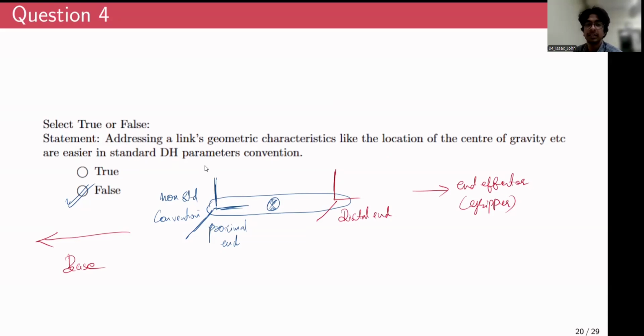So the major thing some people are still going for standard representation is that in that general transformation matrix i minus 1 Ti, there is only a single index i for the standard DH. But in the case of a non-standard representation, in case of the transformation between i minus 1 frame to ith frame, there is a mix of i and i minus 1 indices.